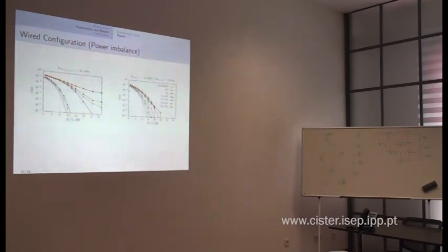For example, we put in some nodes with -5 dBm and then -10 dBm, and you see this 5 dB power imbalance allows you to get the curves right back on track as you would like them to be. And the errors diminish quickly with the signal to noise ratio. Every time we measure one of these curves, it is only 2 nodes transmitting. Of course, it gets worse if you put 2 or 3 or 4 nodes.